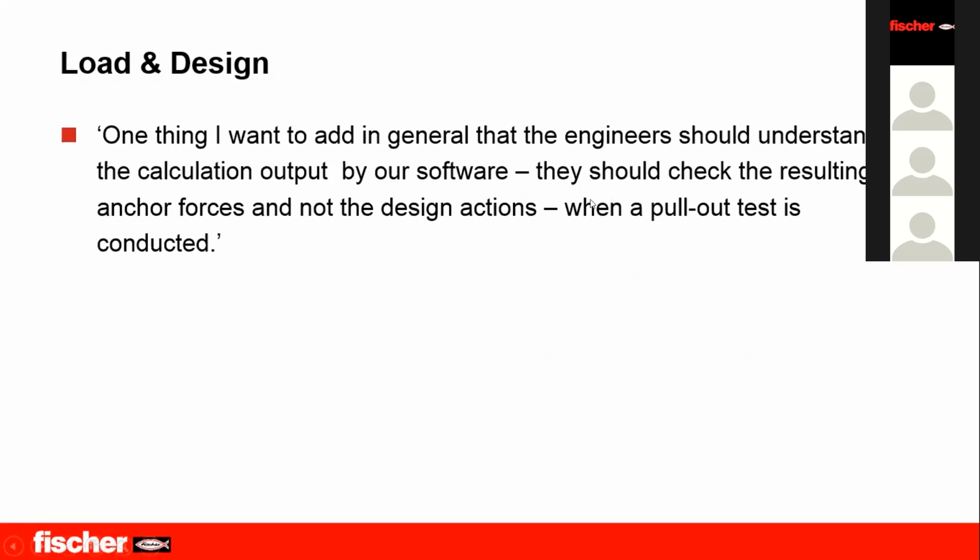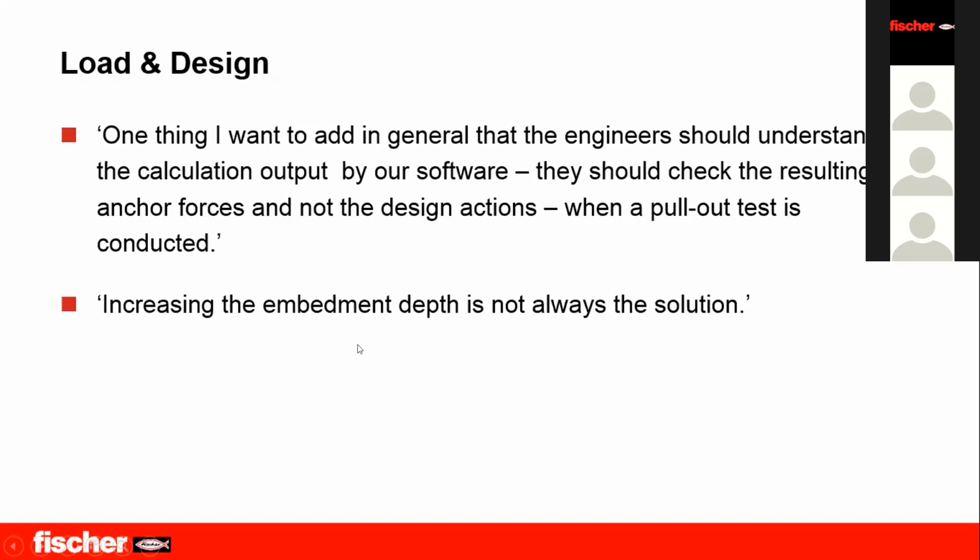They should check the resulting anchor forces and not the design action when a pull-out test is conducted. We will see this in the next slide. The second important point I want to focus on is that increasing the embedment depth is not always the solution. The anchor may fail if you increase the embedment depth because of some other factor.